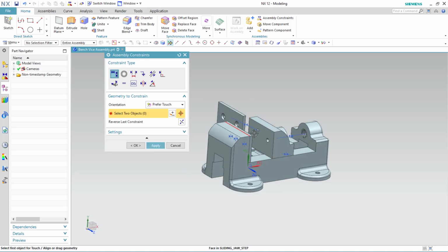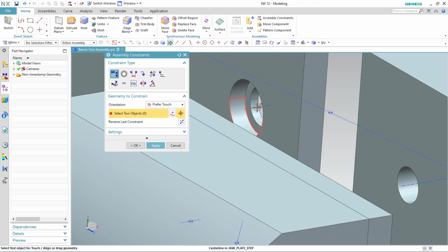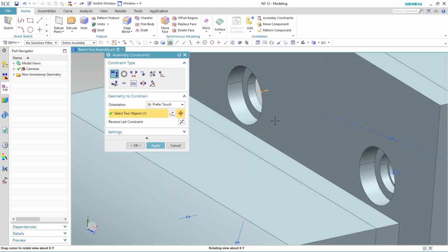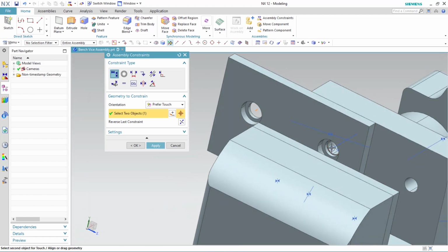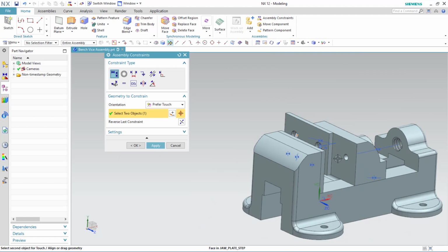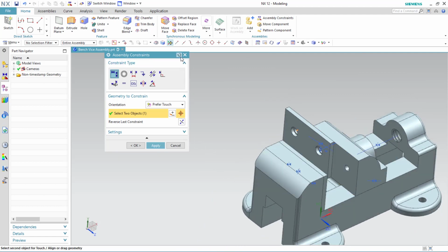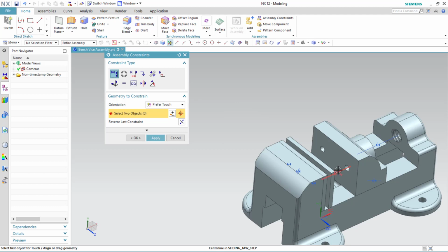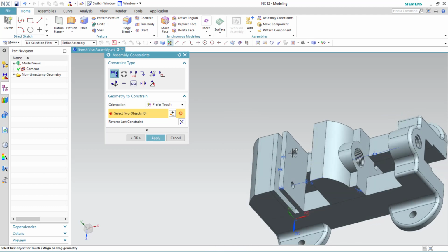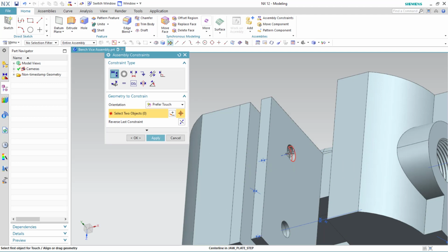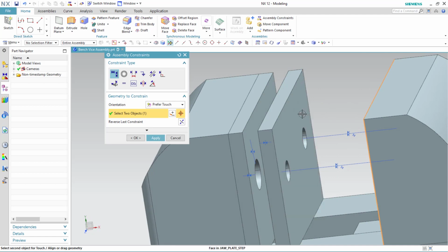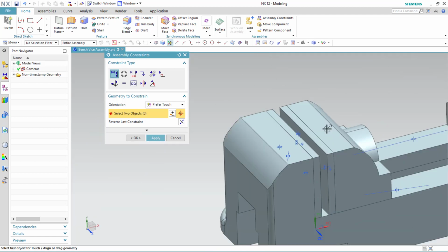faces. This is touch mate. Now the align mate with respect to this axis, and here these two axes. Okay, here I might need to remove this mate. You can reset it, or else you can switch to the mate tab from the feature manager tree, and you can just delete that mate, or you can edit the mate if possible. Better way is to simply reset and assign the mate here only if you make some mistakes while assigning the mates. Okay, yep, so this is done.